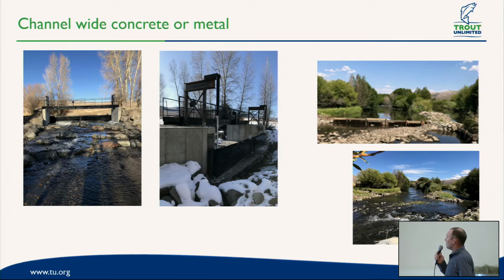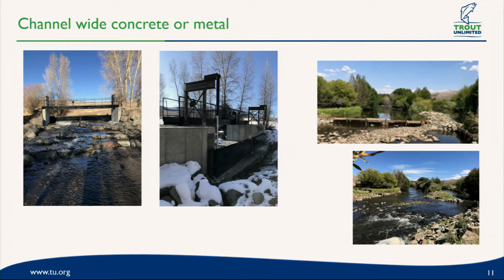So this one, because of how it was positioned on that corner of the stream and the amount of elevation needed to get water into the ditch, rather than doing a permanent rock structure, because we'd have to check it up about 4 feet, and just the amount of material and high flow events is going to want to try to jump outside the banks when you check it up that high. So we went with this kind of innovative design where it's actually a channel-wide gate.